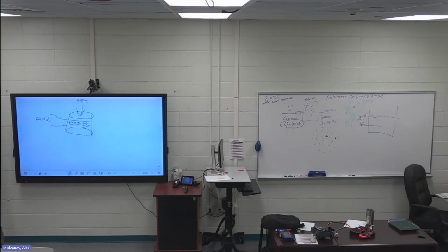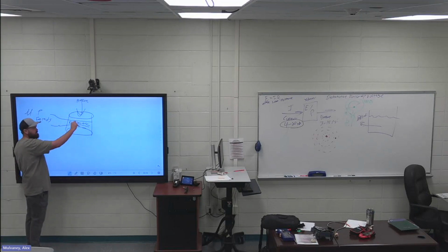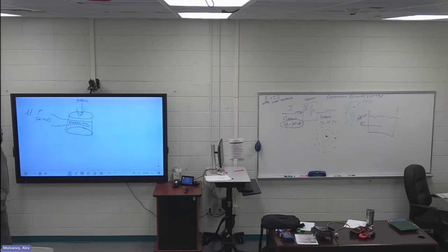Farads. Usually micro or pico farads, it's very minimal. That is how you measure capacitance. So the more pressure I push on this, the closer those plates are together, and it determines a capacitance that we can change into a pressure or a weight, right?